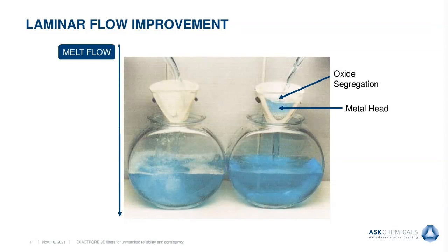When analyzing or reviewing laminar flow improvement of molten metal through filters, one can use water modeling. Before simulation softwares were available, many steel foundries used water modeling to simulate any issues with turbulence or reoxidation in their runner systems or casting cavity. The kinematic viscosity of water is very similar to many ferrous alloys.